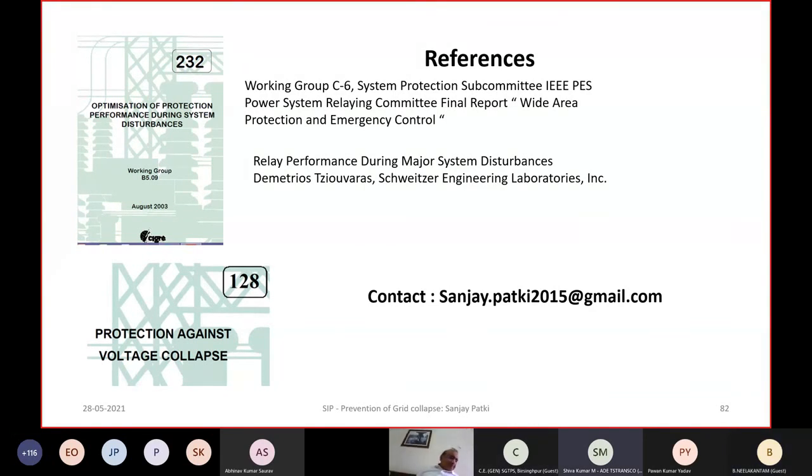Sir, while calculating stabilizing resistance, can we assume zero source impedance so that I can get the maximum stabilizing resistance value, and I can avoid the replacement of stabilizing resistance due to change in fault current because of network expansion? And what is the minimum recommended current setting for REF protection, sir? We are keeping 2% as a current setting, but under through fault conditions, in some of the substations, it is operating.